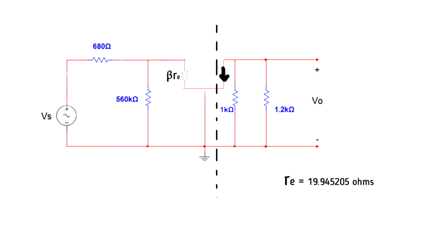Now let's divide this circuit in half, right about here. This division divides the input side from the output side. We're gonna focus first on the input side. The Zin is the sum of all the impedances on this green side. So in order to find Zin, we need to simplify this circuit first. Let's start with this side here, the base area of the transistor. You need to solve for the total impedance in this base area.